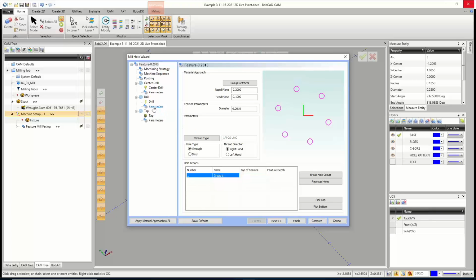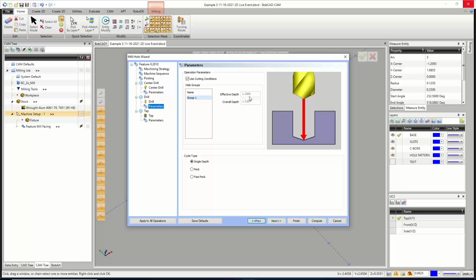So this is actually going to add on the extra 50 thou still, which I'm fine. We'll go that extra 1/4 inch deep, but the center, the tip of the drill is actually going deeper. So the number we should output in the code is going to be this 1.3104. So we do want to make sure we take that into account and we do it that way.